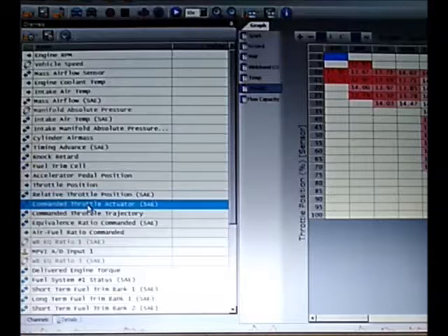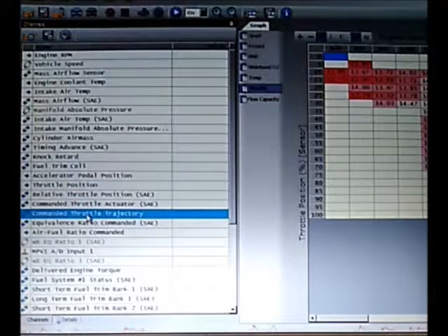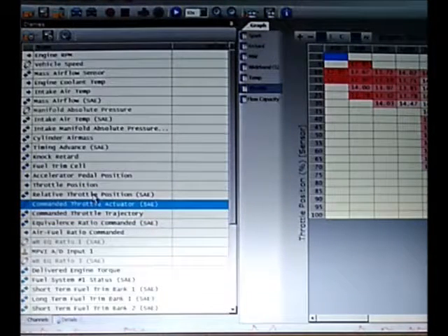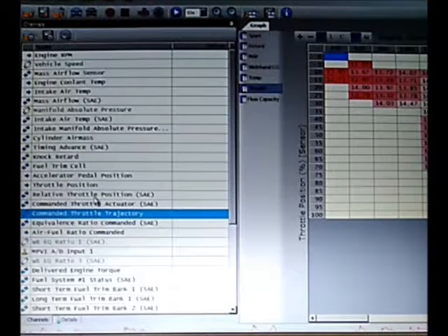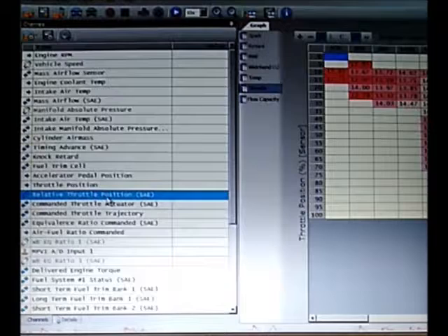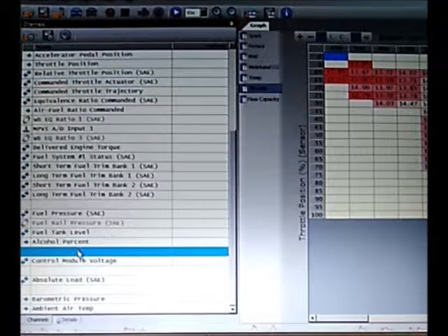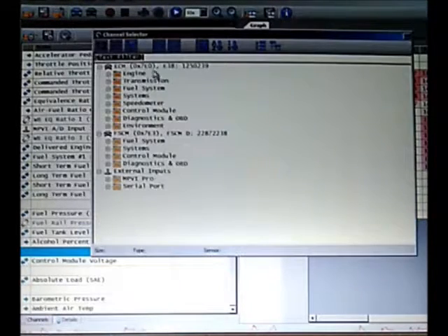All of these ones here, most of them are redundant. You only need one of the throttle sensors. So just type throttle into the menu when you add the PID. By the way, to add a PID, sorry, I forgot to mention this. Pick an empty row like this, right click and go to add channel. It'll bring up this menu like you've seen before, and just type throttle in there.